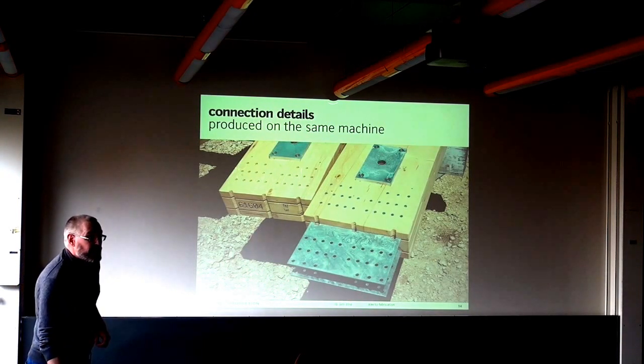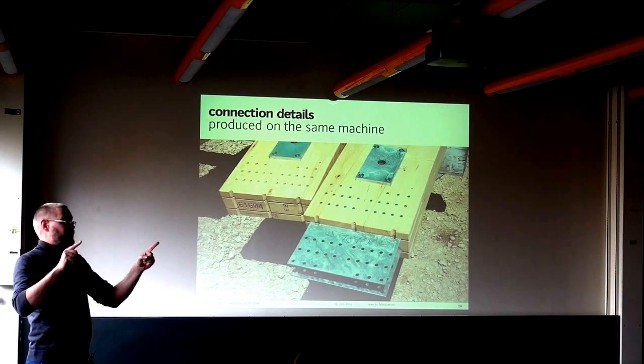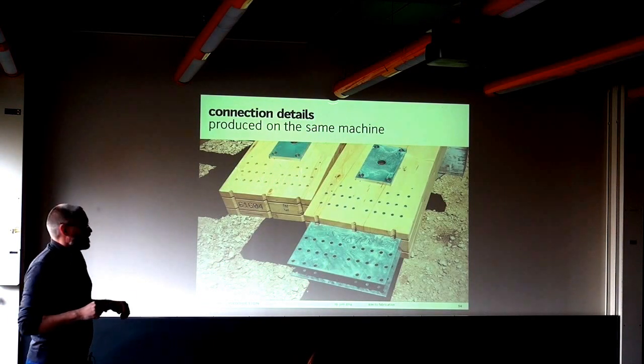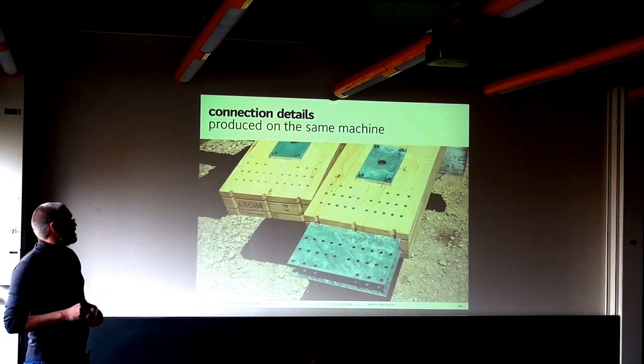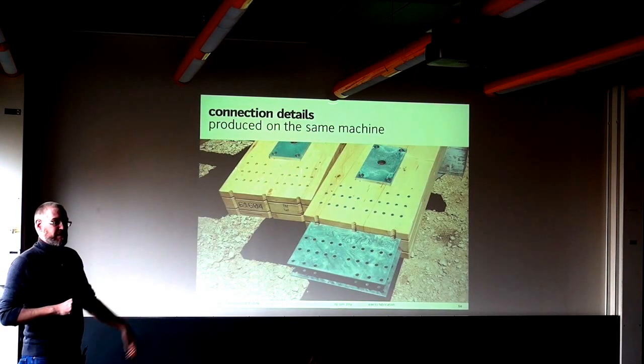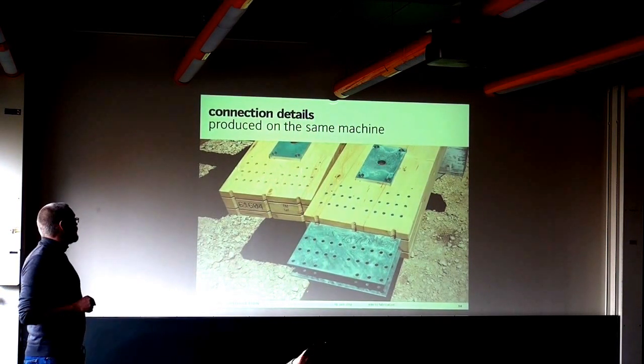What dimensions are we looking at? Thicknesses? The beam is 14 by 44 centimeters. The dowels, I can't really tell, but roughly 12 millimeters. Steel plates probably 6 to 8 to 10 millimeters, depending on where they are and how bad the loading is.